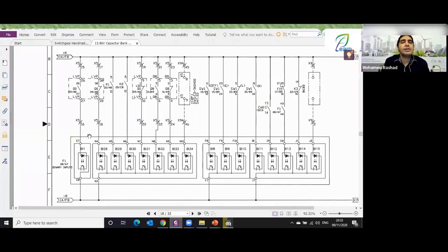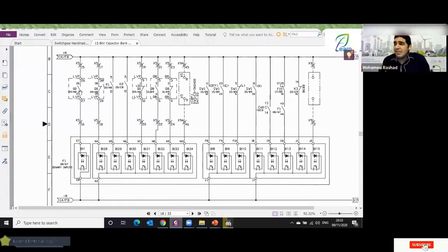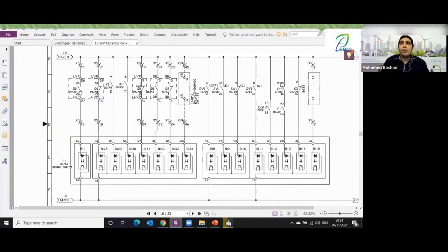Depending on how I will use this information, I can use it to create an interlock, for example, by saying that this information means that the breaker spring, for instance, is not charged. So I create logic within my relay to tell it not to close the breaker as long as you have this information. This information means that the spring is not charged. Okay, I am the one who directs what this information means.